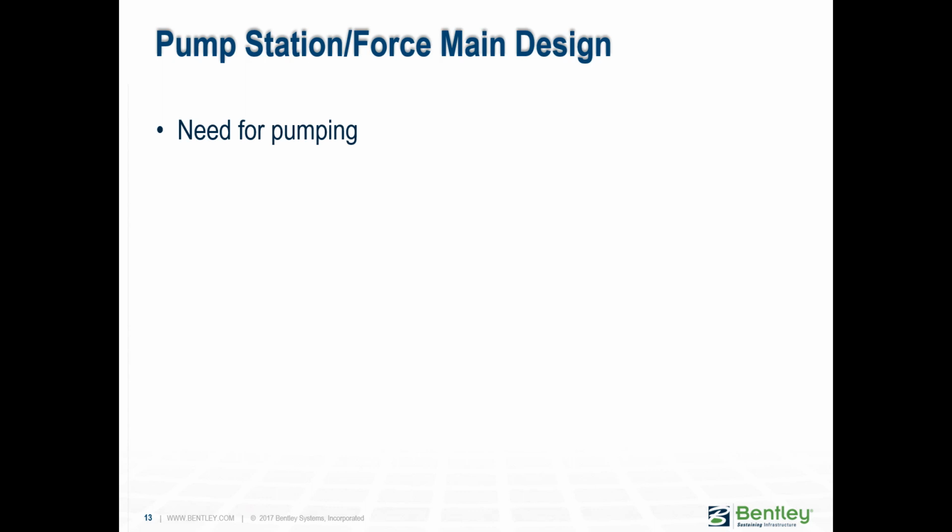So if you're tasked with designing or sizing the force main and also the pump station, there are a few things that you need to consider. First and foremost, is there a need for pumping? Because as we mentioned yesterday, we always aim for systems that would be gravity fed, so you don't have to worry about spending any money pumping water. So make sure that the need for pumping is there.